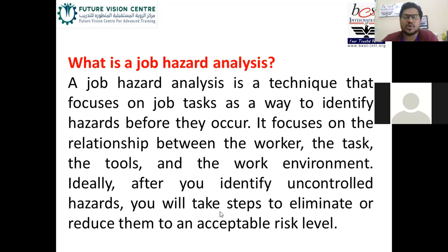It's not like today you have two cranes and you believe it's the same condition, while the next day you have 10 different cranes. So it's not a similar situation now. So according to the addition or management of different kinds of changes, you have to review your job safety analysis, your risk assessment, and your joint site inspections will even be redone. So all of these elements are not just a one time exercise, where you make the documents and keep them in a file.